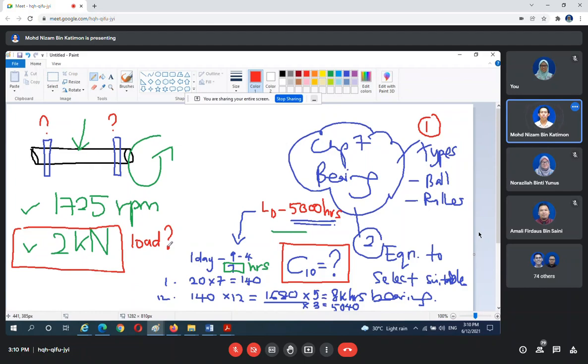How we select 5,000 is not a big deal, as it is just some logical calculation of hours, desired life, desired speed. The issue is the load, because the desired load is based on the problem. Again, this reflects your fundamentals of solid mechanics, meaning how to find the proper load based on the free body diagram and so on.